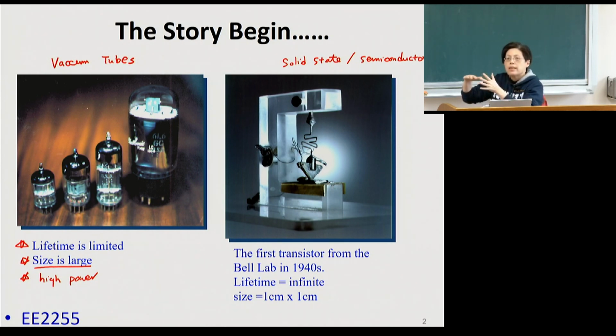The reason why, in the early stage of semiconductor technology development, people used germanium-based devices a lot is mainly because it's easier to refine, because germanium melts at around 900 degrees C. So you want to make it pure. The purification of material is very important in making semiconductor devices. So people start with germanium because it is one row downwards, so it's actually a less robust material. So you can actually purify it much more easily.